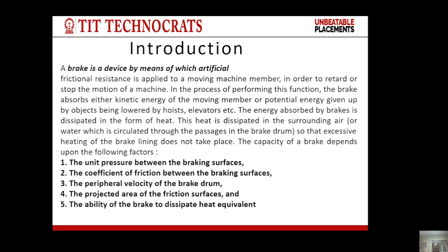First, introduction of the brake. A brake is a device by means of which artificial frictional resistance is applied to a moving machine member in order to retard or stop the motion of the machine. In performing this function, the brake absorbs either kinetic energy of the moving member or potential energy given up by objects being lowered by hoist, elevator, etc. The energy absorbed by the brake is dissipated in the form of heat.